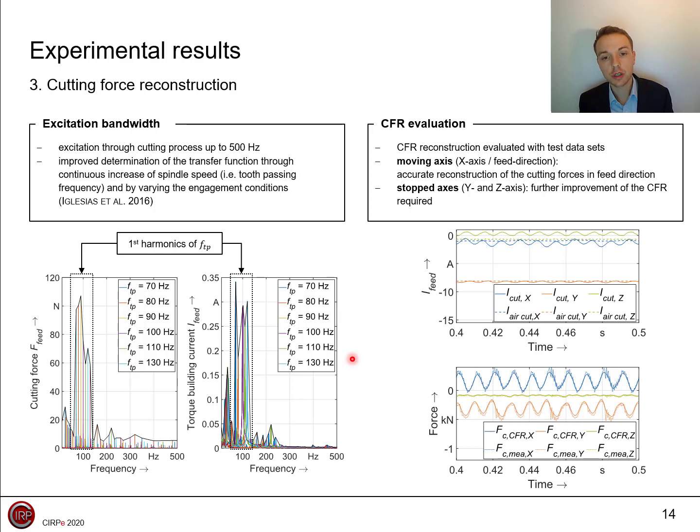However, as the figure on the right shows, cutting forces could be reconstructed based on the measured motor currents. In the moving axis, the x-axis in our test setup, the reconstruction of the cutting forces already worked well, and a good agreement between reconstructed and measured forces could be observed. In contrast, the reconstructed forces in the stopped axis showed greater deviations due to larger influence of friction, and the reconstruction for the stopped axis, in our example the y and the z axis, must be further improved.